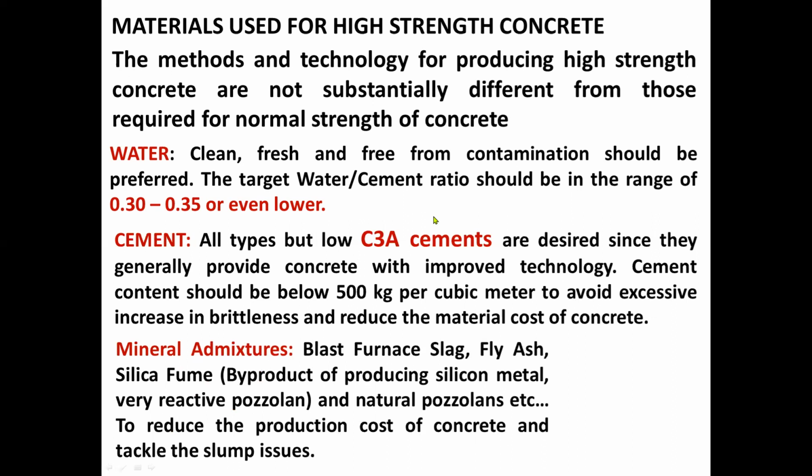So kailangan inaaluan din yan ng mga admixtures na tinatawag natin. Let us say we have the blast furnace slag, fly ash, silica fume. Ito yung ginamit ng mga Indiano sa pag-construct ng sample ng concrete na qualify as high-strength concrete. It is actually the byproduct of producing silicon metal. Very reactive pozzolan din yan. Actually, meron tayong tinatawag pang Silicon Valley of India kung saan may maraming silicon and natural pozzolans, etc. to reduce the production cost of concrete and tackle the slump issues.